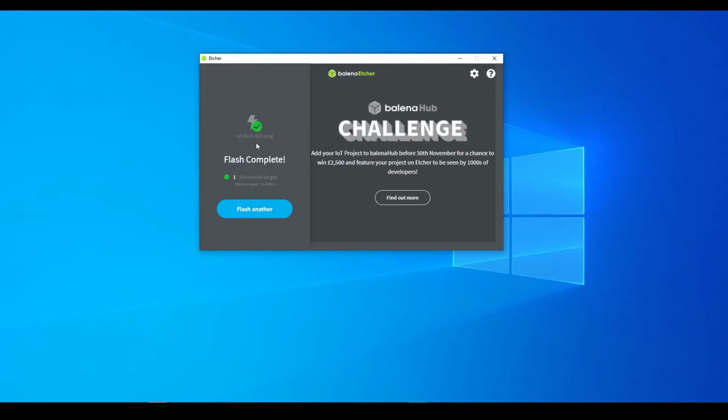After it's complete, you can see that a lot of things are popping up, because the memory card is now more suitable for use with the Jetson Nano. It's not for a PC to read, which is why your Windows doesn't recognize it. So what you need to do is remove your memory card properly and close all the pop-up windows. So I'm going to remove my memory card here.